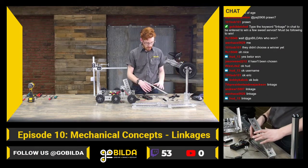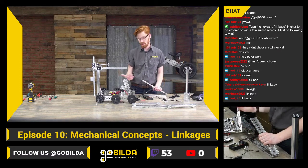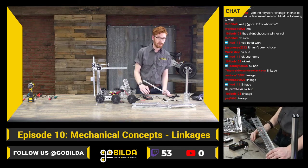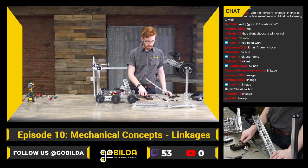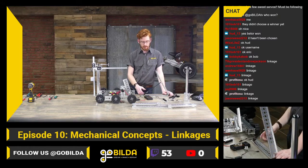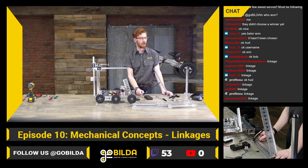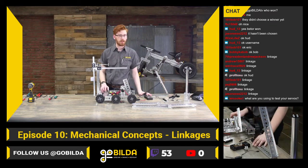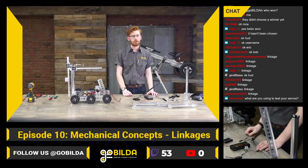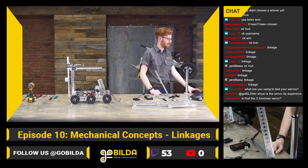So, that is really the primary use case for linear servos. You can, of course, use them to move something linearly. I think within FTC, for most applications, when you are moving something linearly, they're fairly slow. So they're not going to be the greatest option. But when you're doing something like this, where you commonly need a lot of torque, this is a great way to get just a ton of torque without drawing very much power. These will run right off the expansion hub, or if you want a little more juice, you can run them off the servo power module. Contrary to a lot of servos, they're not going to draw any noticeably more current off the servo power module.